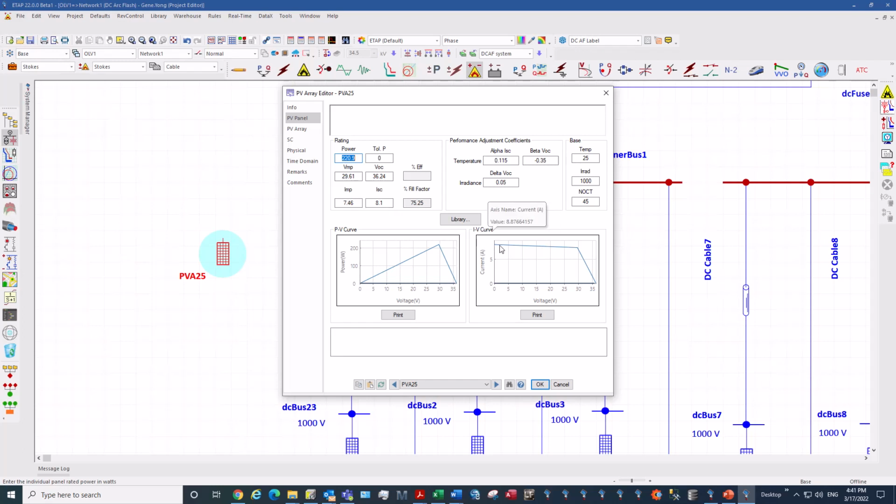So as you can see on this IV curve on the right, we have this I short circuit, the V open circuit, and this knee point, which is the maximum power. This plot also correlates to this PV curve, where you can see that this maximum power point is delivered where you see on that IV curve. And so this is called the linear three-point model. This is when you do not have a library defined, and you can tell when it's not defined when you don't have any heading in here.